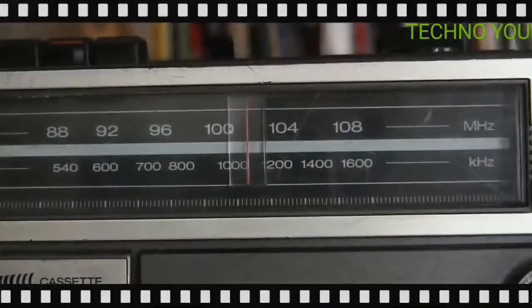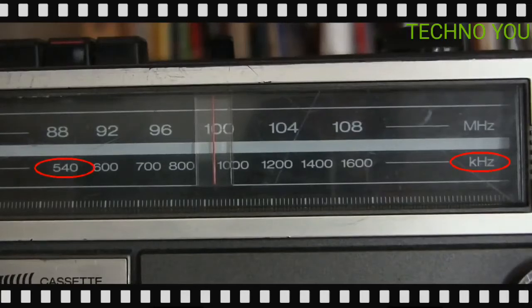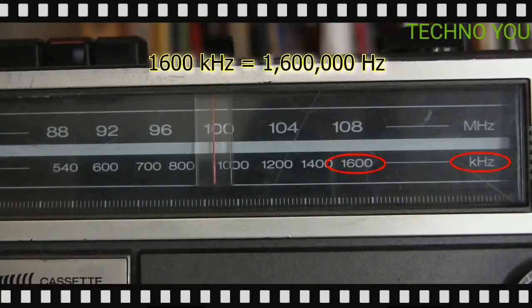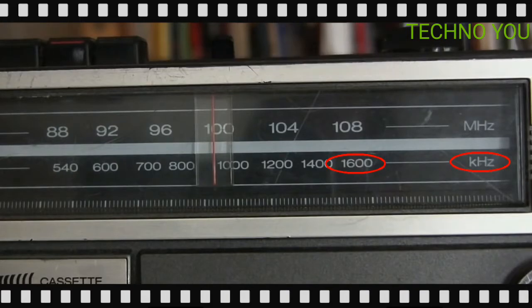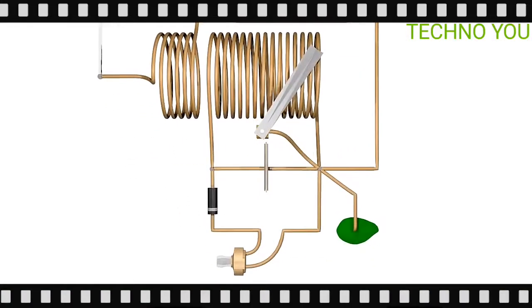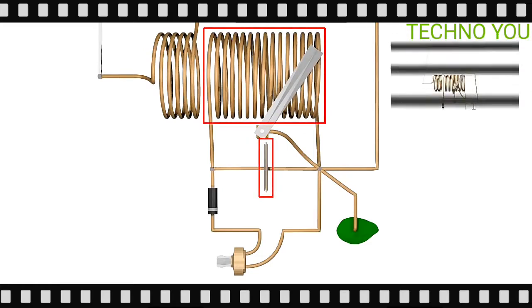Actually, AM radio waves have a much higher frequency. If you look at the dial in a regular radio, the frequencies it can tune into range from 540 kilohertz, or 540,000 hertz, to 1600 kilohertz, or 1,600,000 hertz. So the waves arriving at our antenna are all at different frequencies. Listening to all those frequencies at the same time means you'll hear all the radio stations at the same time. That's where the second coil and capacitor come in. They allow us to tune into, or select, just the radio station we want.